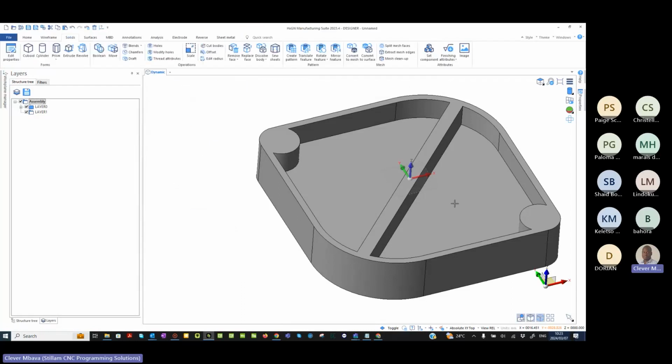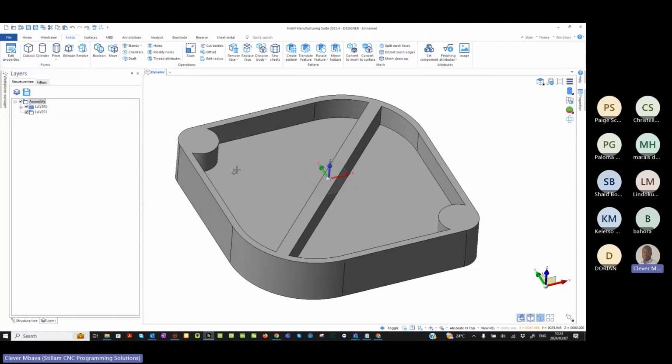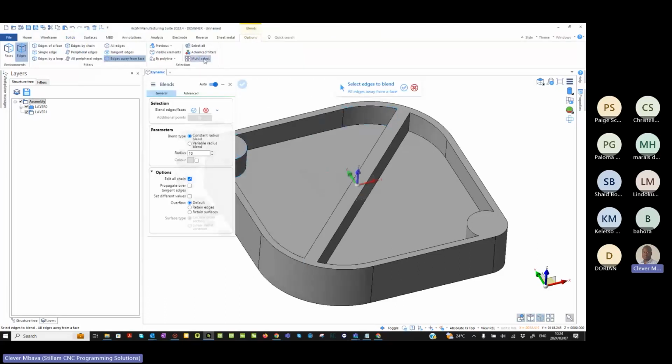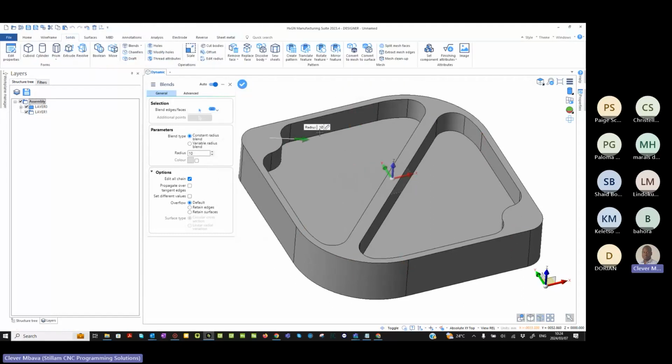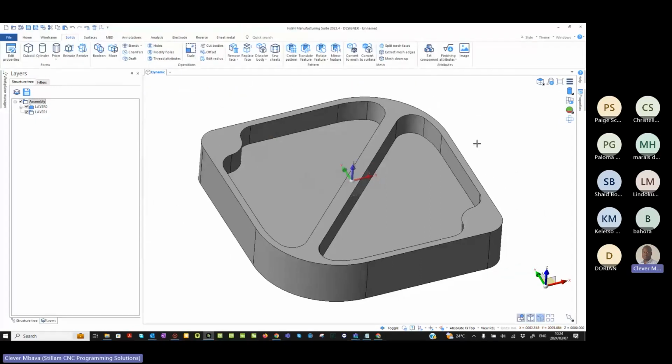All of those options. You can see, while I can show you one way, there are multiple ways of you to achieve what you need to. Then I can quickly go and say, I need to give blends or fillets. And I go and say multiple selects. And I say in here, edges away from face. Pick up that face and this face, right click. There is my size or my fillet being applied in there. I can confirm that. I'm happy with that.